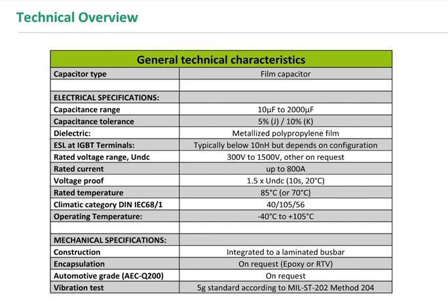Definitely, as experts in laminated busbars, we can make suggestions on how to improve the design of a busbar, and by taking a capacitor versus an active element and putting it on the busbar, we create a kind of subsystem. We take care of at least the two components, busbar and capacitors, because we have to know that the inductance contributors are definitely the busbar.